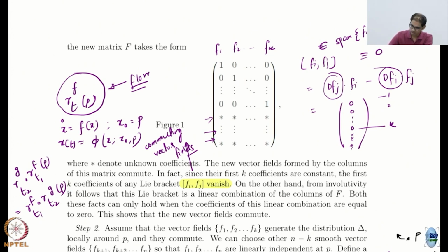If you say linear system case, x dot is Ax, x dot is Bx, the Lie bracket is easy to compute. If f1 is Ax, f2 is Bx, the Lie bracket is exactly AB minus BA. Not difficult, you can think about it, just a thought experiment.